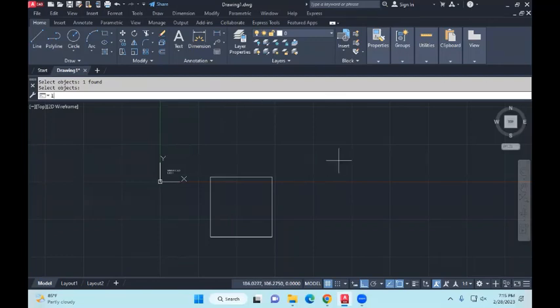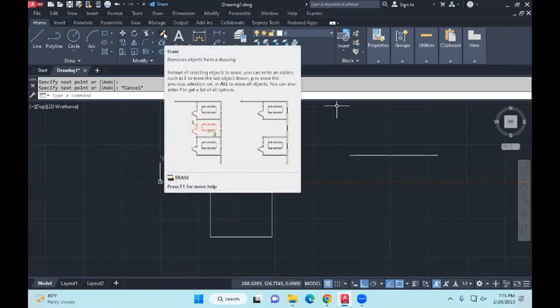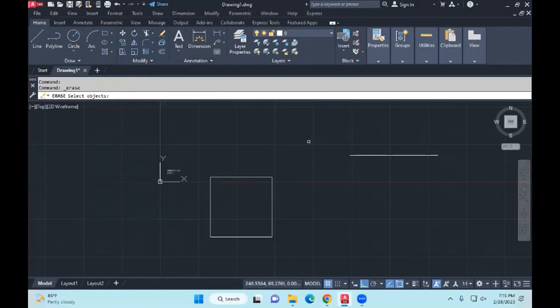Or we are used to deleting things, right? So for a horizontal line, you can use the erase button as well. Where it says modify on the dashboard, there is an eraser symbol on a pencil. You hit that, whichever part of the drawing you'd like to erase. If you move your mouse over it, an X symbol automatically pops up. Click on it, and keep track of what the command box is telling you. It's saying select object. You have selected that line to delete, press enter. So that's how you erase or delete things. Or the simplest way is to select that line which you want to delete and hit the delete key on the keyboard.